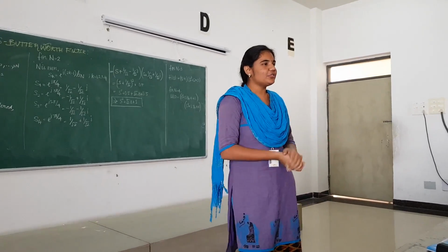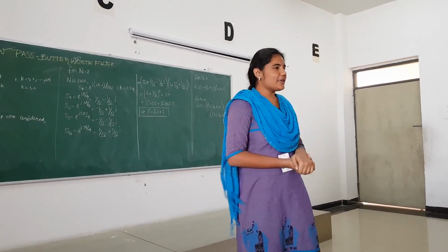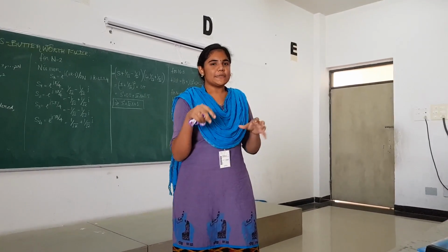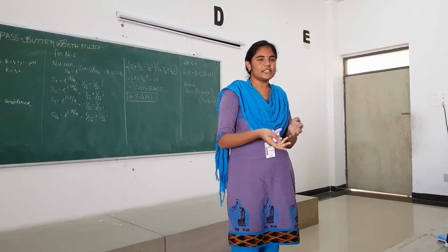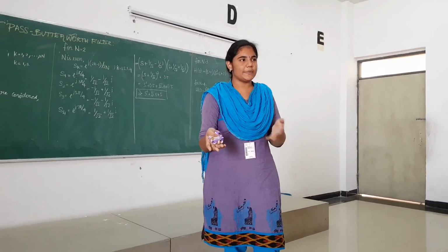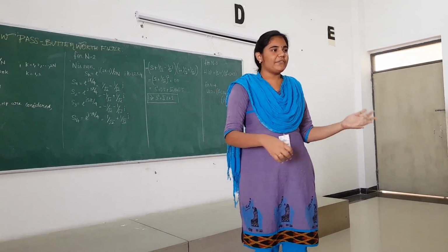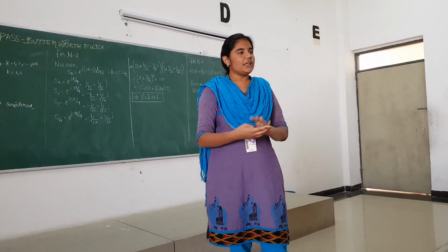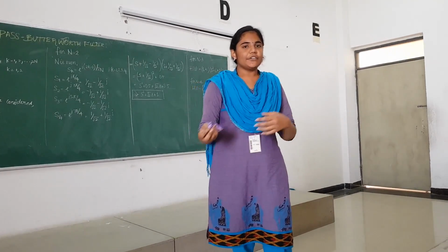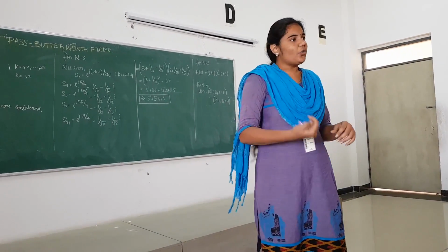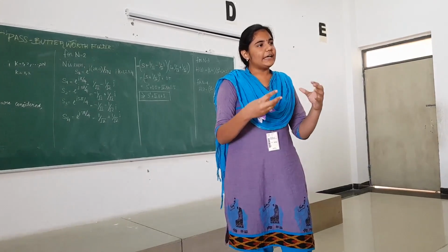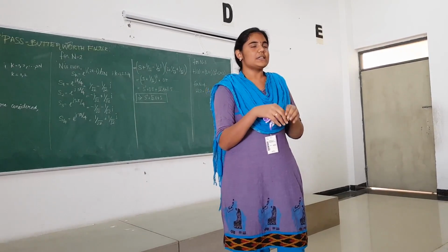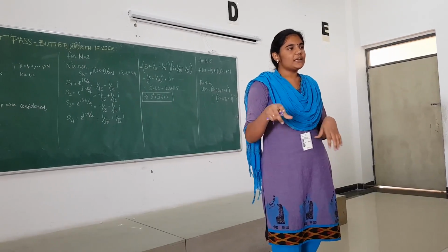I'm going to share something about the real-time applications of digital low-pass Butterworth filter in differential data processing. Let us consider a pneumatic cylinder. The piston displacement of the pneumatic cylinder is measured by using a displacement sensor, and then the speed and acceleration of the piston are obtained by using differential amplification on the displacement time curve. If we process this curve directly, the error is very large and the curve drifts overall. So we interface the curve with a digital low-pass Butterworth filter. If we interface these both, the error becomes low, and the distortion is very less. So this shows that with the low-pass digital Butterworth filter, the speed is valid.